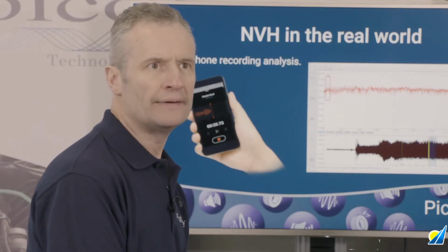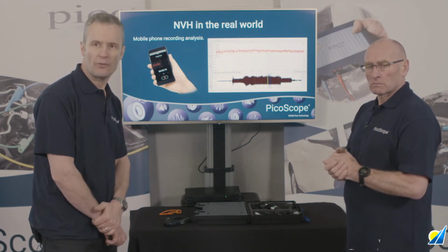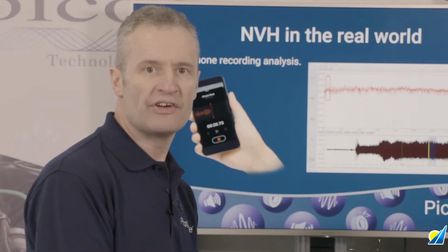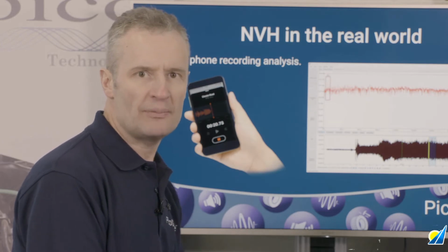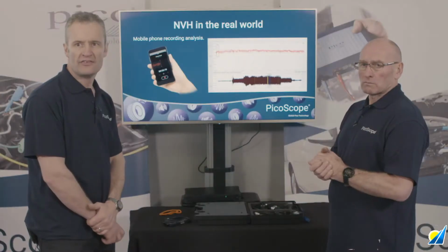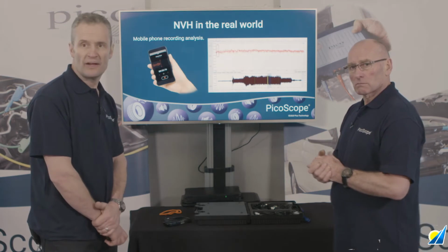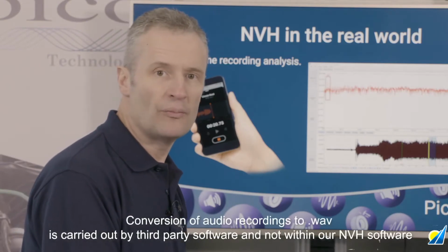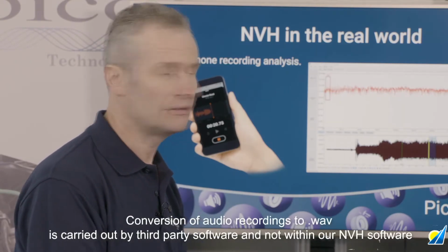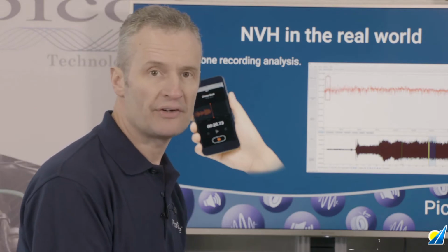As a technician, we're all often faced with intermittent problems. These are events that occur very infrequently, very intermittent, with no pattern to them. Often customers will bring in recordings of events, whether that be a video or an audio recording. That is incredibly useful from an NVH point of view, because if we ask the customer to record an event that's happening with their vehicle when it's safe to do so, we can use NVH software to import that audio recording. We have to convert their recording from whatever format they've recorded into .wav, but once we've done that, we then analyse all the data exactly as we would if we'd recorded the same sounds with the NVH microphone.